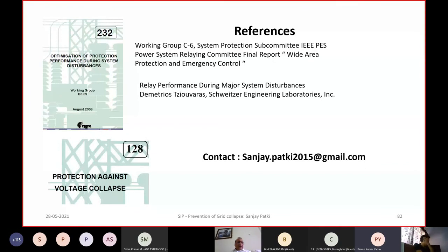No, as I said, there will be some mismatch because of CT performance. In ideal condition, what you are saying is correct, but practically there will be some mismatch, and for every through fault, there will be some current flowing due to the voltage developed in all the secondary circuits which we discussed today. That means the CT secondary winding resistance as well as the lead resistance of the cable, etc. So there will be a voltage developed. Only thing is that the voltage developed will be less than the pickup of the relay.